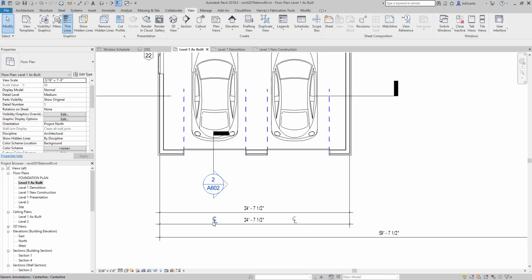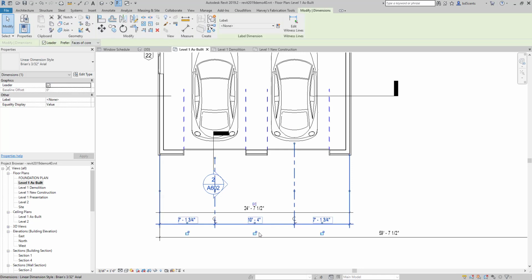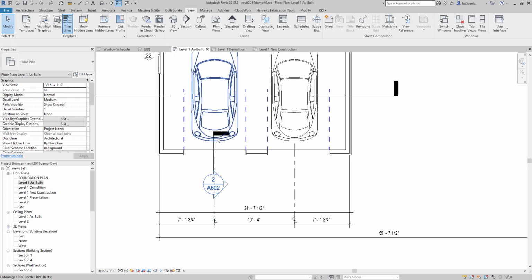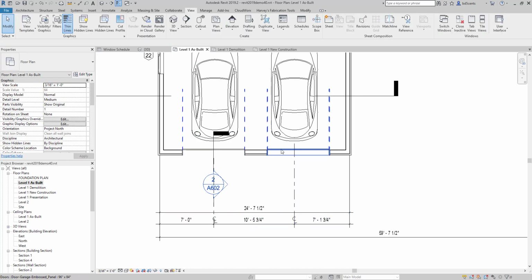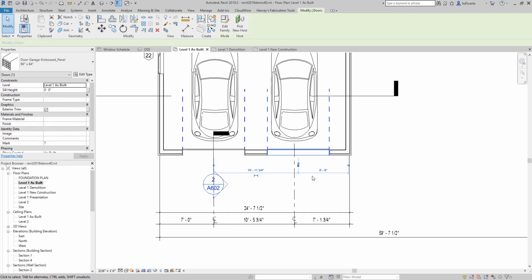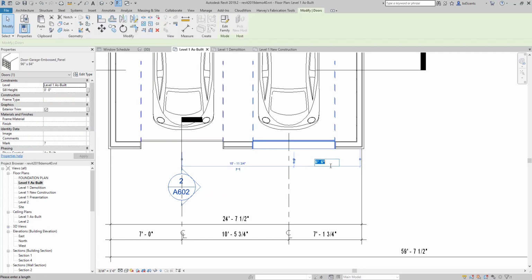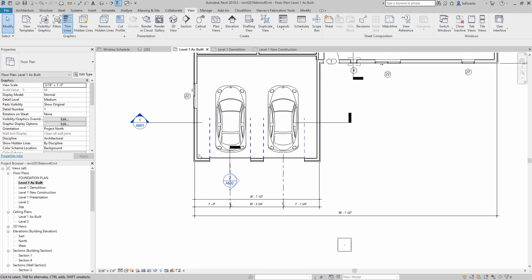We did originally centerline them as shown here, so I could come in and add witness lines to the center of these doors. And then I could hit equal, and they'll be equal across. Or I could change the value from the door here. So I could say, okay, I want this one to be 7 feet, and I want this one to be 7 feet. It's not working for that one. That happens sometimes. Let's see where this one's at. 6 foot 10 1/4. And we'll go ahead and hit, that's good for now.